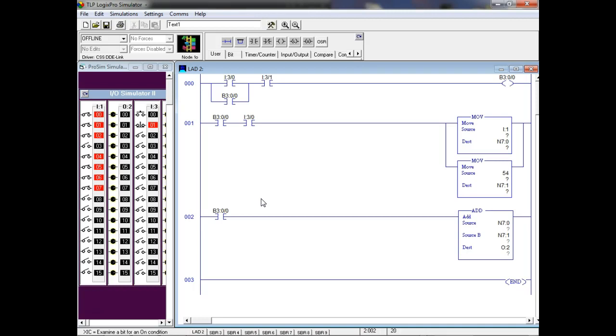There's only one timer that doesn't reset automatically. Your on-delay timer and your off-delay timer reset themselves when you do what? Not when you lose power, when you disable. Yeah. So you were resetting something that didn't need a what?